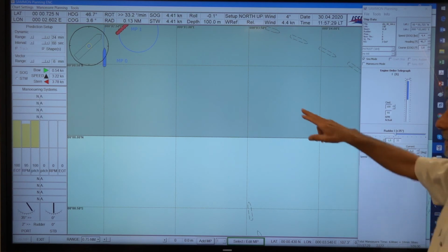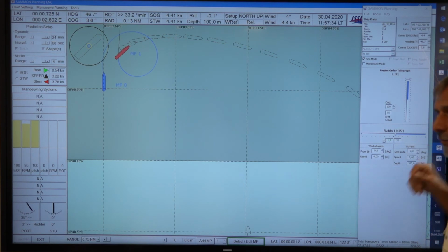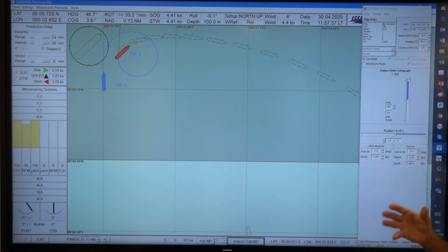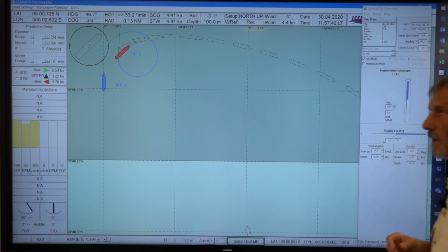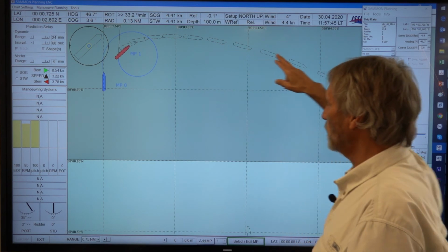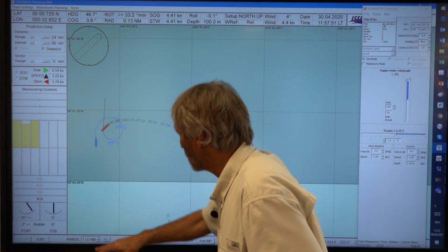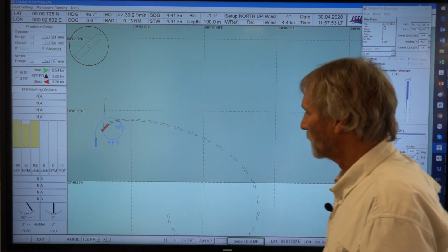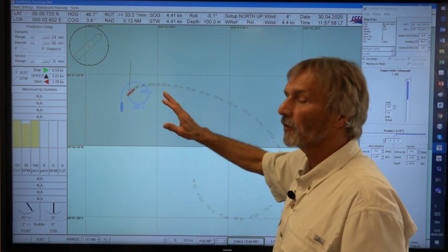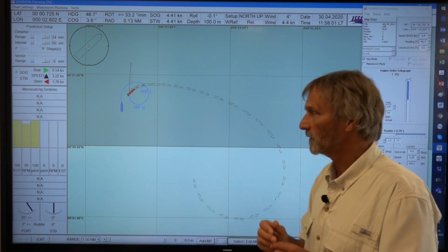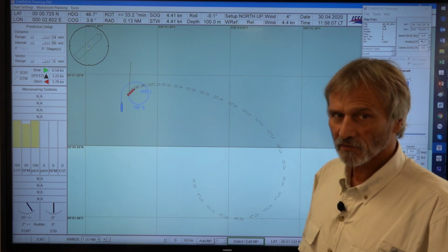So the ship is going into a turning circle. 1.8 was the neutral, the rudder angle of neutral effect. And you see, it doesn't help. The ship continues to turn. You would even see the full picture here. So this is the turning circle. Here we put the rudder amidship, and not amidship to the neutral effect degree, but still the ship is continuing to turn and goes into the turning circle.